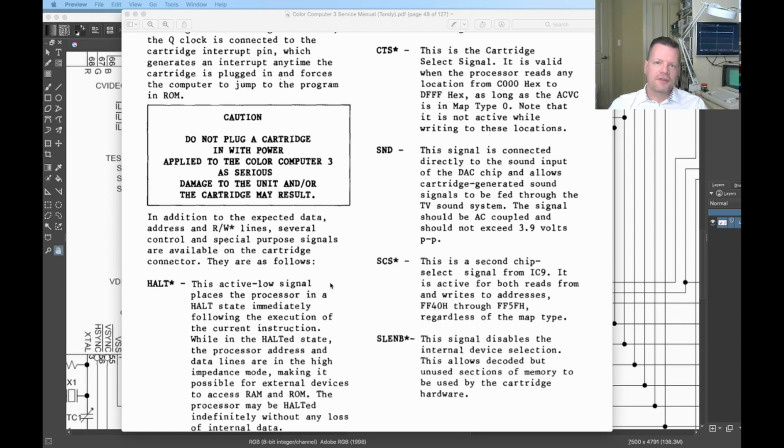The challenge is that these enable lines, from the computer perspective, need to only be enabled when the computer's accessing specific memory locations or specific addresses. In order to do this, you need to do something called address decoding. To do address decoding, you take your 16 address lines that are coming in from the CPU, and you'd use a series of digital logic chips, so AND gates, OR gates, XOR gates, in order to create a mapping between the 16 input lines for the particular address that you wanted to one output line, which you would connect into your chip to enable it.